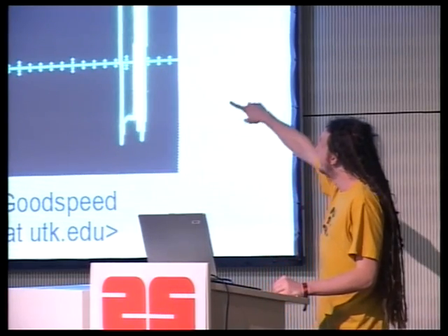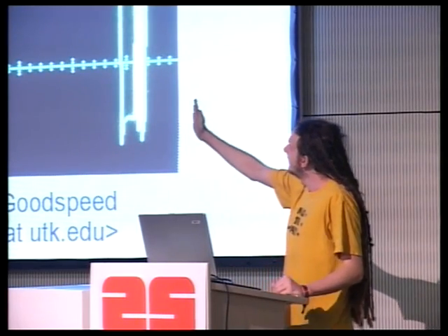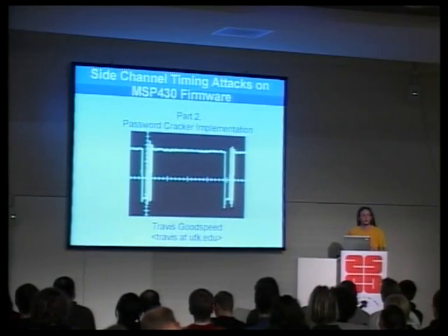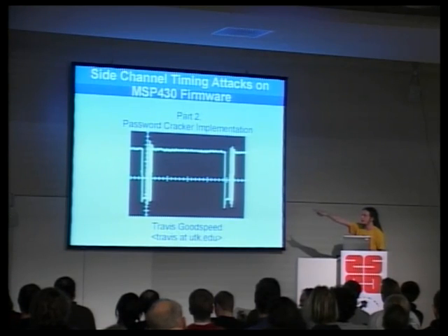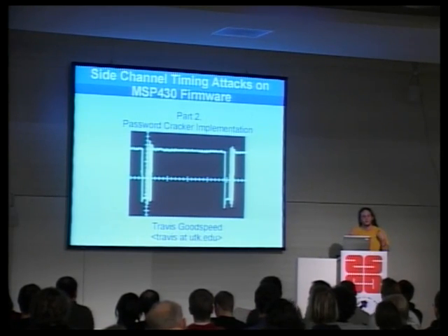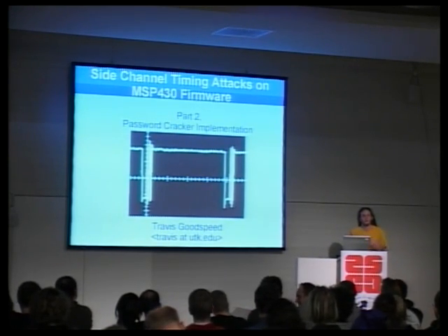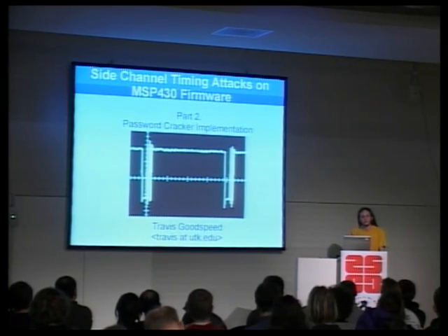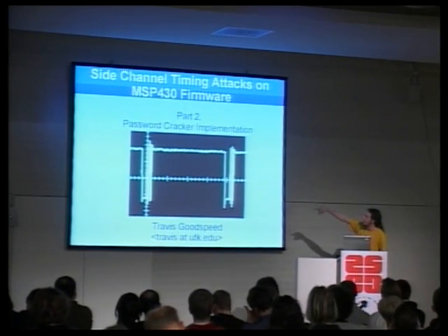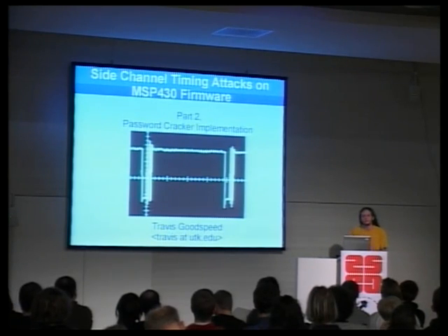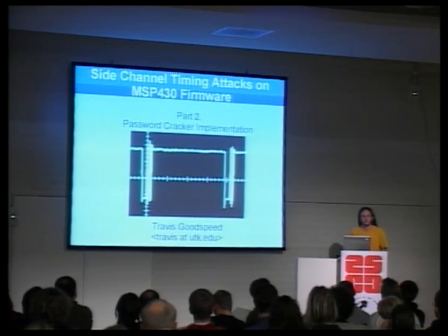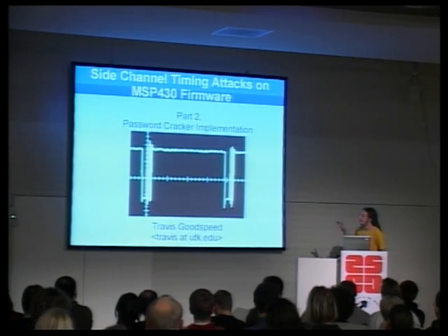If you look at this waveform on the title slide, the left is an acknowledgement telling the attacker that it's okay to transmit. Between the two signals, the attacker is giving a password guess, and he's doing it with non-standard serial timing. Then the right waveform is the victim telling the attacker that the password is wrong, and that he's not going to be given access to protected memory.